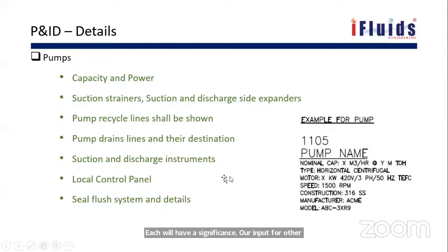Examples: field to blind connection, connection for used oil vessel drain, pipe should be free of pockets and stagnant areas, you should mention a slope there, complete respooling of lines may be required to tie in new lines. All this gives specific instructions. The field to blind connection is mainly for maintenance. Connection for used oil vessel drain is for normal operating.